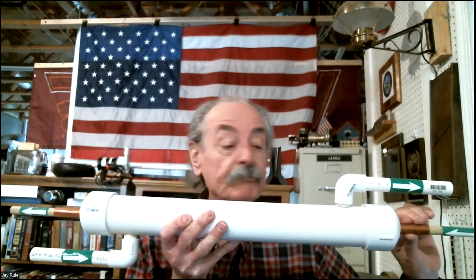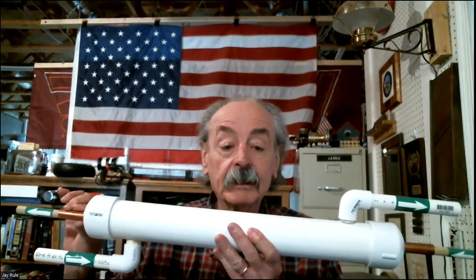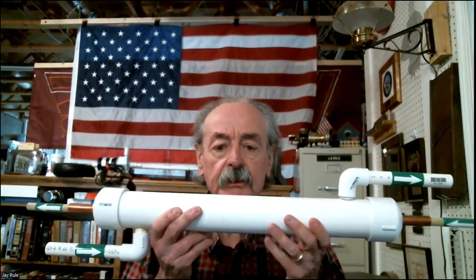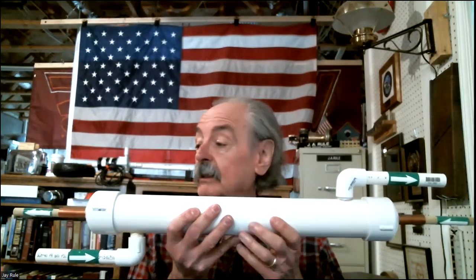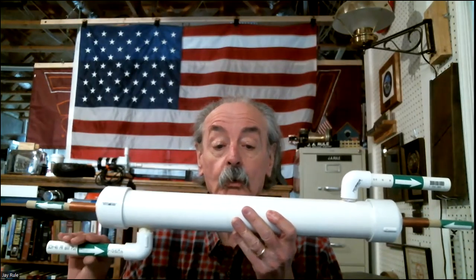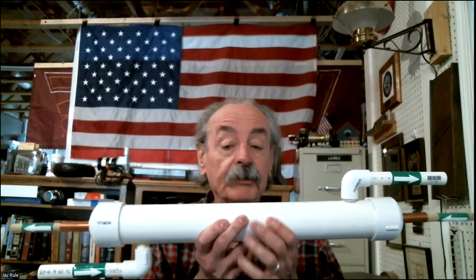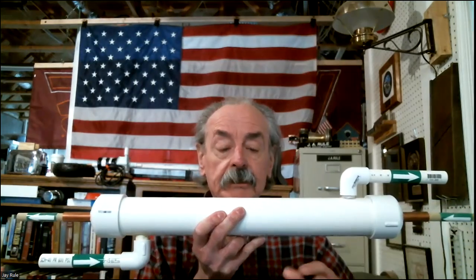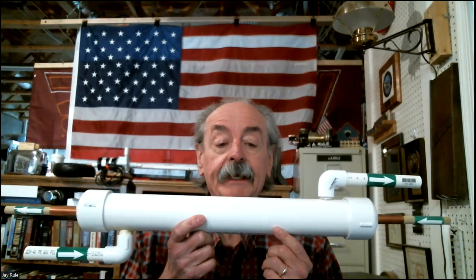We've got a hot fluid coming in and leaving, but it's cooling down because what's surrounding that copper tube would be cold fluid. We'd have cold water, say, coming in, absorbing heat from the hot fluid and coming out here. So this is just a model of a very simple counterflow, what we call two-pipe heat exchanger.